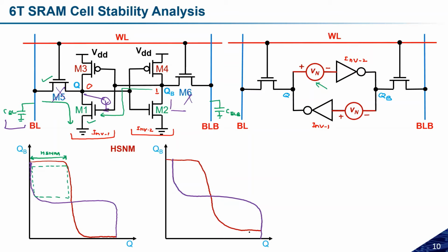Yes, this potential difference plays the important role in reducing the noise margin. So the important thing is that during the read operation we have to optimize our circuit in such a way that this lower margin, whatever we are observing here, should be as small as possible. If we reduce this voltage difference, in that case we can increase the noise margin.